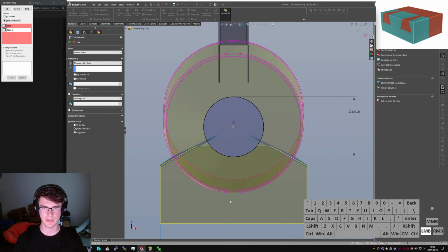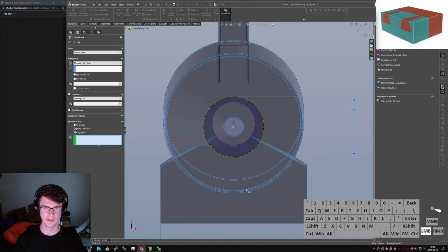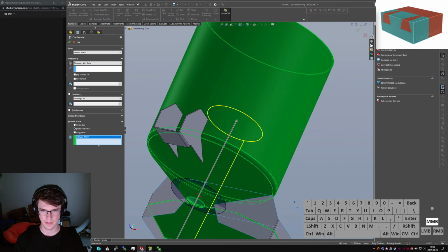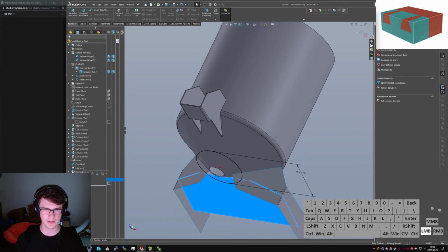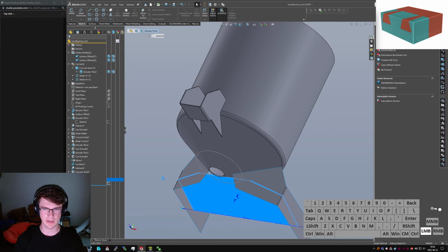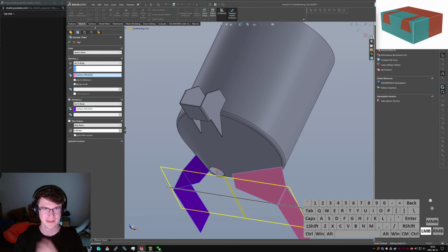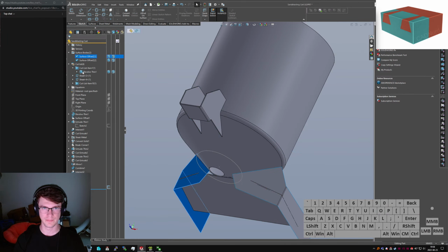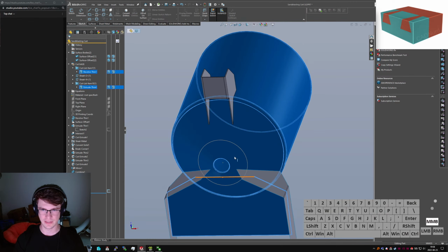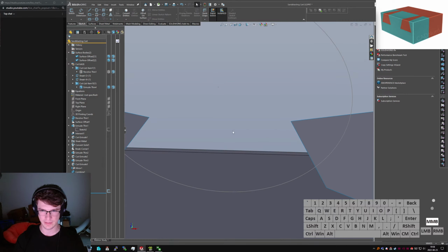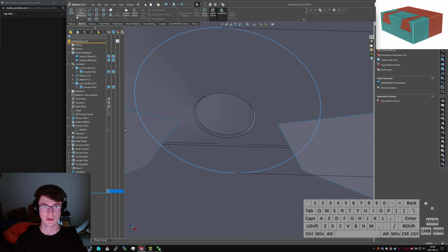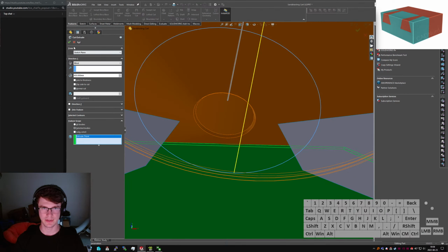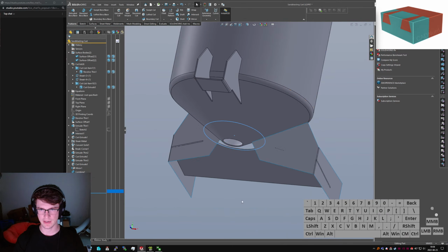Whoops. Nope, just selected bodies. Or cancel, hang on. Gotta change the feature scope there. Oh, hang on, it merged. Gotta leave this sketch and come back here and say don't merge with anyone. There we go. It made these two into one part, but now I can hide them separately, which is what I want. So come back here, features. Nope, not whole wizard. Extruded cut. Don't auto select, just pick that one. And now we've got clearance.